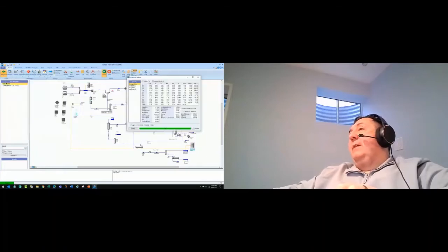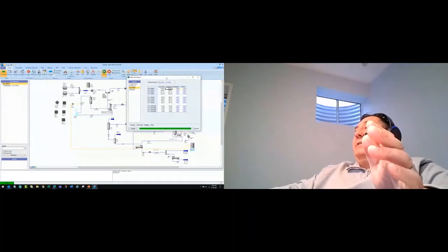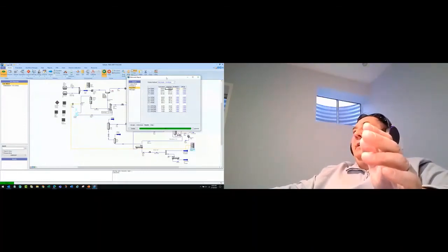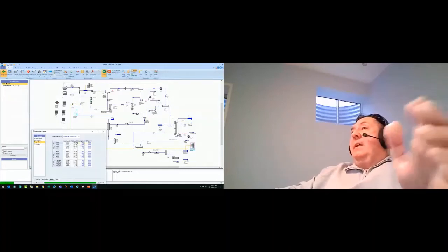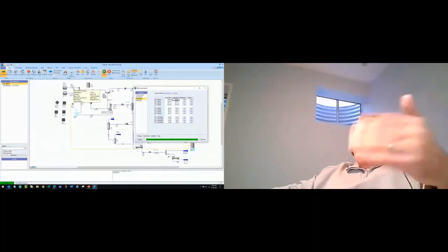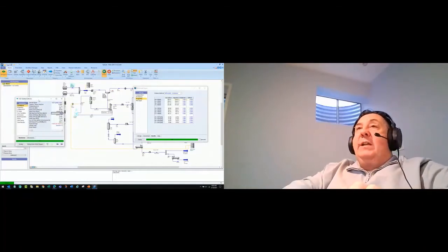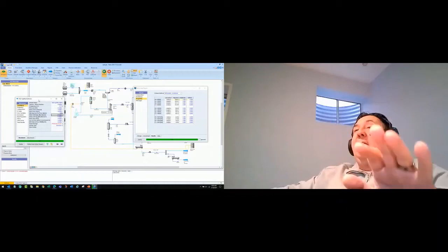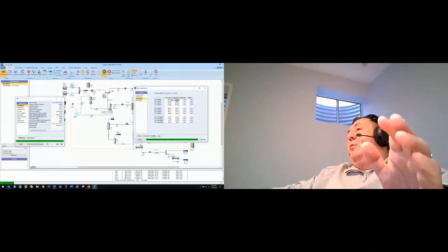of this gasoline stream. And I can see here that, for instance, I have a 100.01 octane number, okay? And that is the result of all of the calculations related to all of the upstream operations here. And by the time I get to this gasoline blending component, I see that I have a 100 octane. Now I can say, well, what happens if tomorrow I'm going to be asked to process 10% more feed? So right now, suppose I have 3,000 barrels per day going into this unit. I have an octane of 99.93.